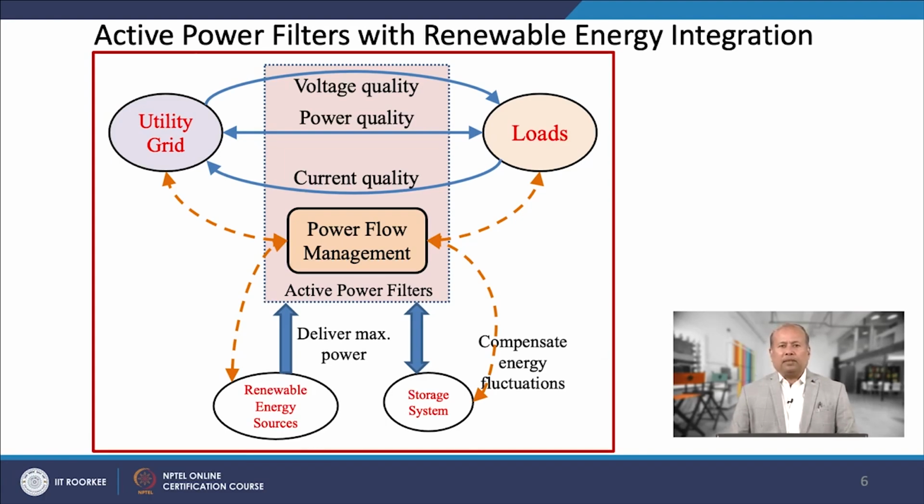To compensate for the energy fluctuation produced by solar and wind energy due to their intermittent nature, a battery storage system is connected at the same point of the DC link. As a result, the utilization factor of the converters will increase, and it can even compensate long voltage interruptions due to the presence of energy storage at the DC link.